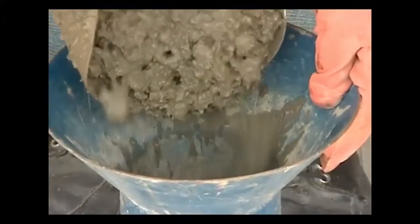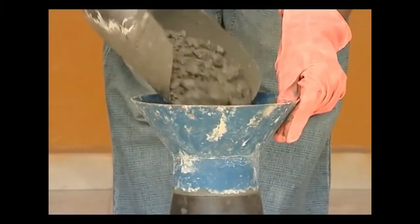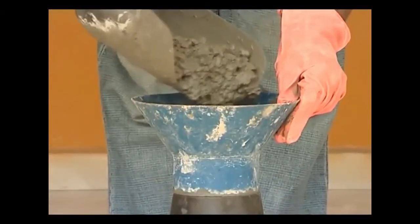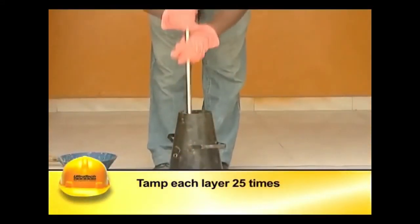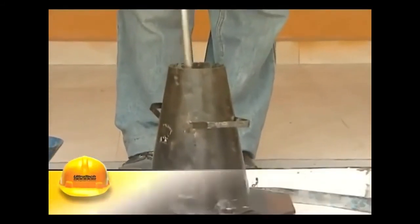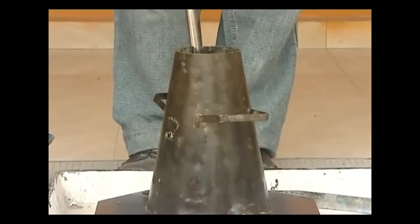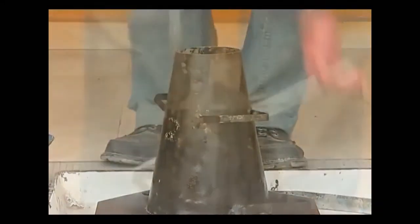It is then filled in 4 layers, with the thickness of each layer being approximately 1/4 of the height of the mold. Each layer should be tamped 25 times evenly using the rounded end of the tamping rod such that strokes are uniformly distributed over the cross section.